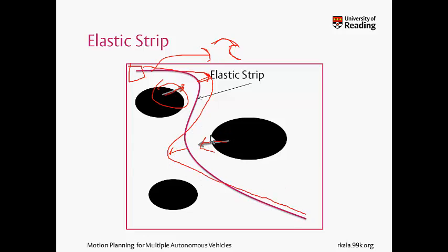So as these obstacles move, there's an elastic strip, and we all know the property of an elastic strip. If you apply force to the strip in this direction, which this obstacle by its very nature is applying, in fact, it's applying a virtual force like this. All the obstacles, we know, repel in potential methods. So this obstacle is applying forces like this, and this obstacle is applying forces like this, because of which this elastic strip is getting repelled. As they continue to move on, the forces will get modified and they'll get more and more repelled.